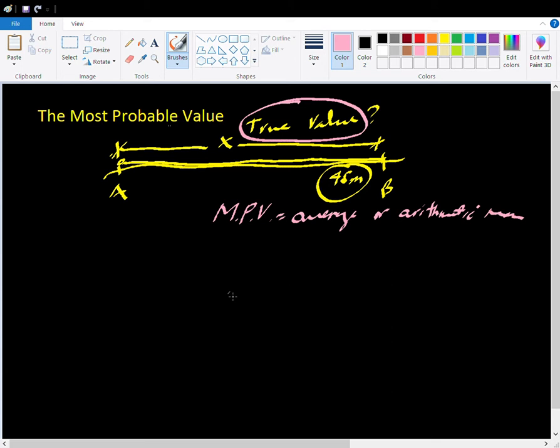The laws of probability presume that many measurements, 10, 100, or more, made under similar conditions will provide us the most probable value. The number of measurements made in surveying, for practicality and for economic reasons, is lesser than 100. Usually we make 4, 5, 6, or 10 repeated trials done under similar conditions.